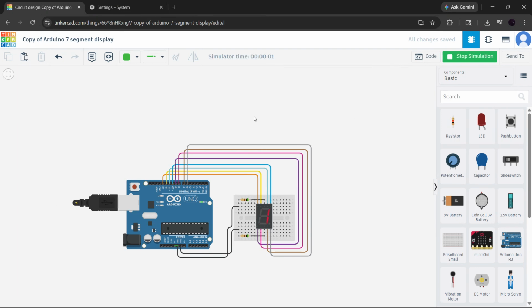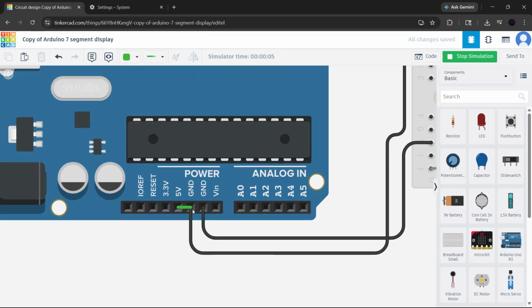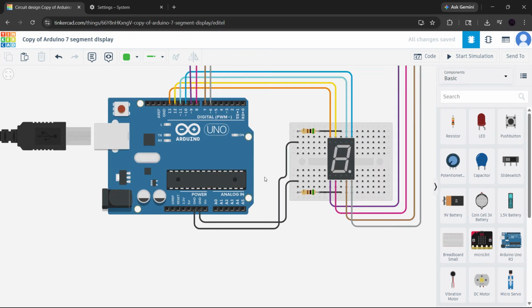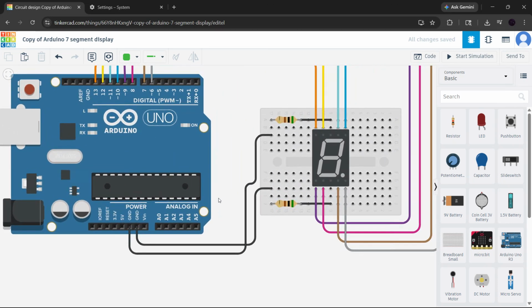To fix this, look carefully at your wiring. Check for any wires that may be connecting the positive rail directly to the ground rail. Also, look for places where a wire may have bypassed a resistor or LED. If you're building a simple LED circuit, for example, make sure the resistor is actually in the path and not sitting off to the side.